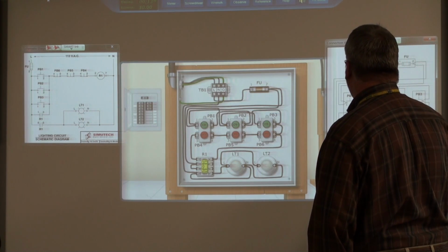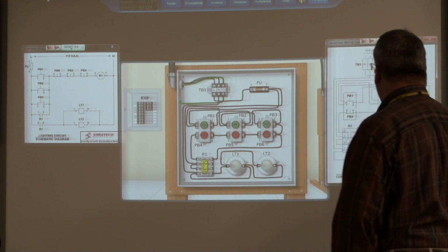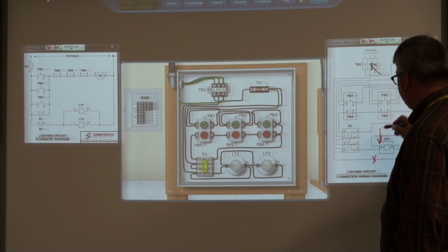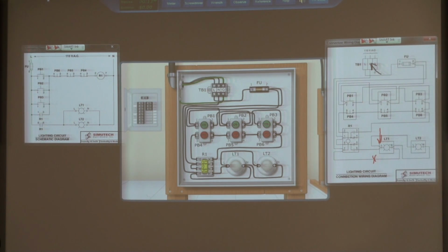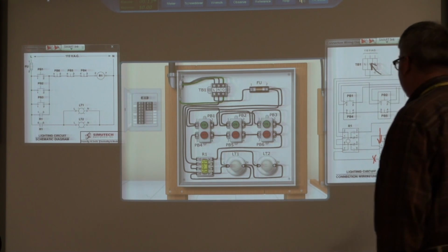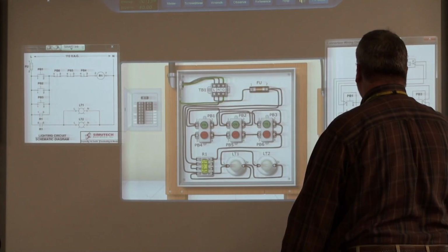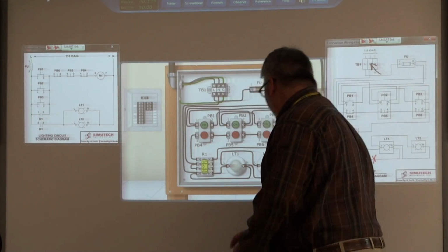Did I put it on the L or N? You put it on the L. Okay, good, that's where I meant to. All right, what would I measure there? Zero. Again, my neutral is opened up to my lights, and I would measure 0 volts.